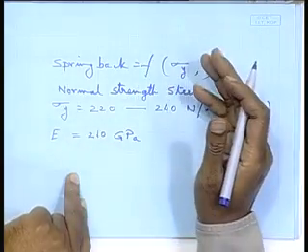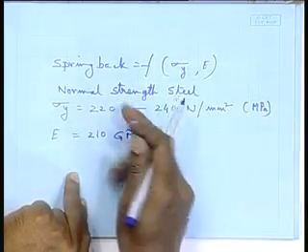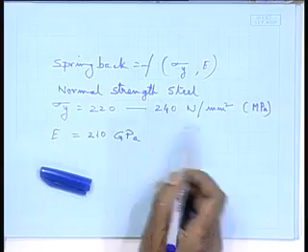If I take an average 230, well, any value you take, your spring back will be different, and that difference could be of the order of several millimeters, and several millimeter difference I cannot tolerate, because say my plate thickness is 8 millimeter, I am making a frigate, side shell thickness, say part of the shear strake at the forward part is say 12 millimeter only, and there this kind of variation gives me a variation of 6 millimeter in the bend shape, half the metal thickness.